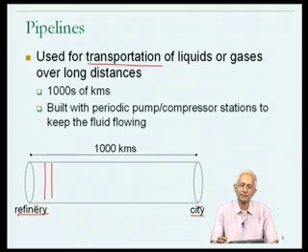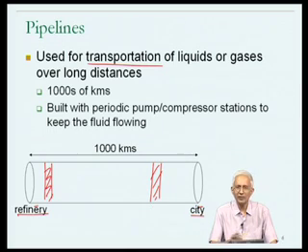through the pipeline. Now, if that is the case, then much of the effort of using the pipeline is going to be spent in pumping air through the pipeline, because at any given point in time there's 20 kilometers. Now the 20 kilometers of airline fuel is here, and it slowly moves through the pipeline. At some point in time it's over here, and in pumping it you are basically pumping air in order to push the petroleum fraction that you have through the pipeline. So this is not a very effective use of the pipeline.